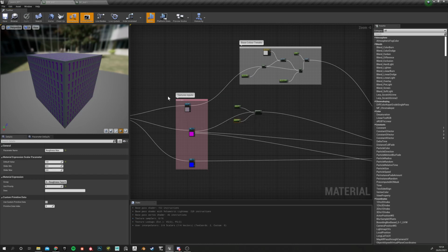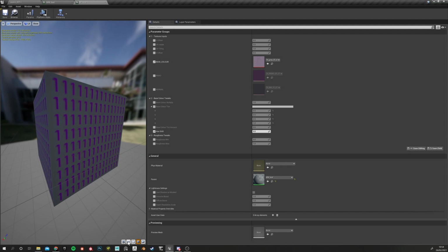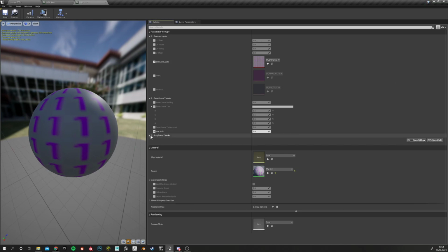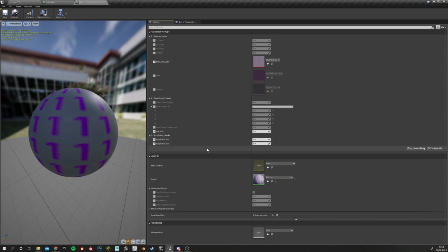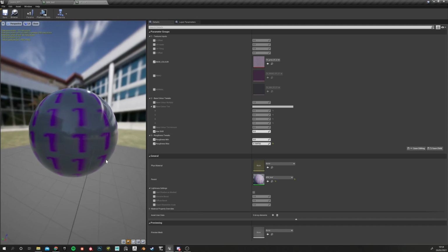Now when we apply this, I can shift or remap the colors a little bit. Look at this. Maybe a sphere will help. On the highlight here, you can see that when this is 50% gray, that's what you get as rough. But now I have an entry called roughness tweak, so I go to minimum and maximum, and if I say the minimum is different, you can see it tweaks everything too bright. If I lower the maximum, you can see towards 0 it gets shiny. So I have the ability to change this.